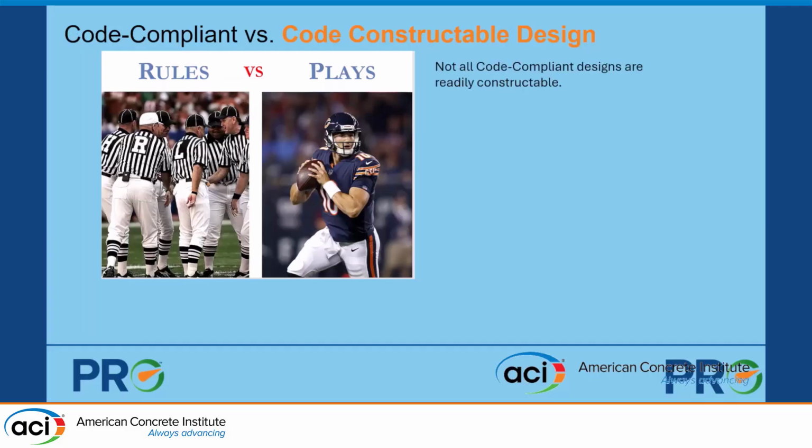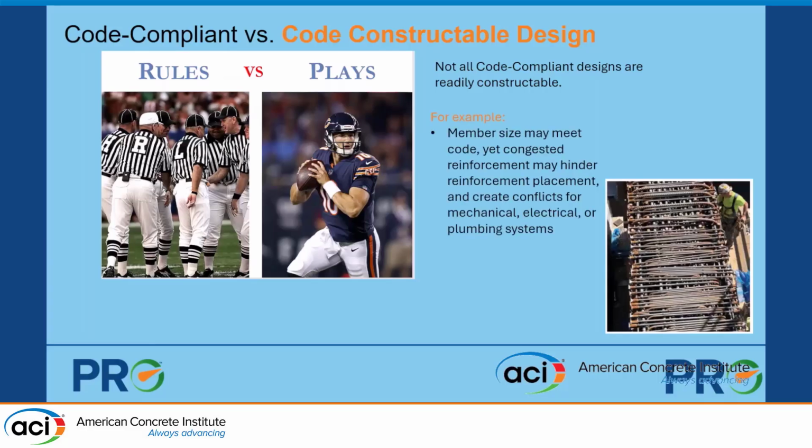As I've heard him say, not all code compliant designs are readily constructible. For example, member size may beat the code, yet congested reinforcement may hinder reinforcement placement, as you can see in the photo. So the message in constructability is not to be outside the code, not to be non-compliant, but to have great plays for the designer to maximize the code for productivity, for efficiency, for time, and for the best value to the owner.